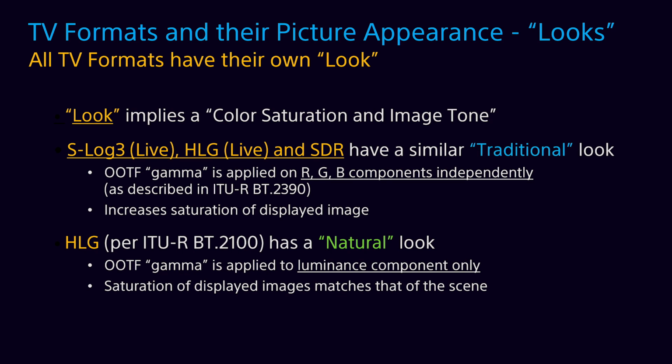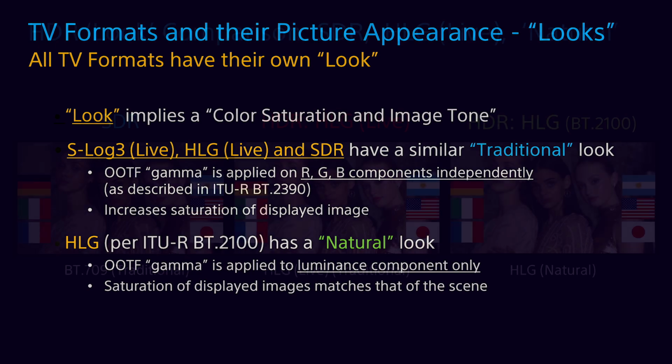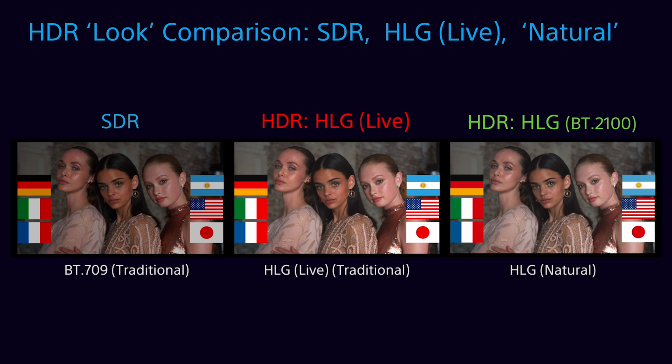The word natural look we use to describe the appearance of the HLG format, as defined in the international standard BT.2100. This signal format applies the look, or OOTF, to the luminance signal only, making the color saturation of the display image match that of the scene. Let me show you some examples of images that hopefully illustrate the differences in appearance of these traditional and natural looks.